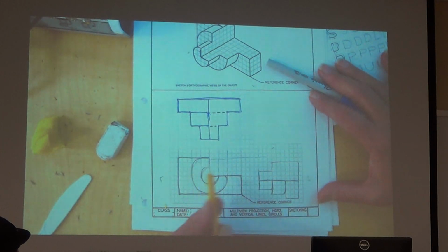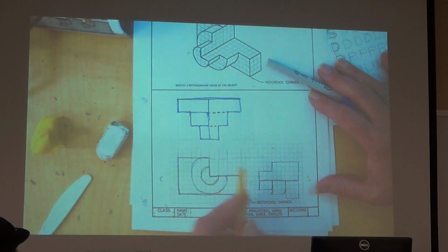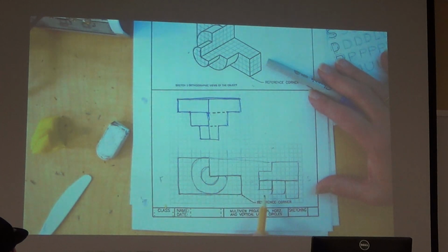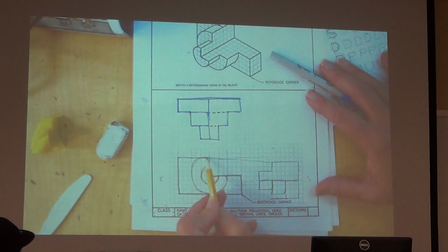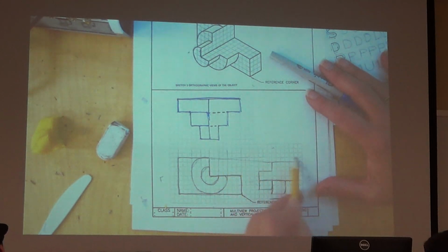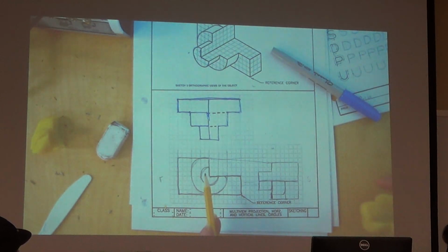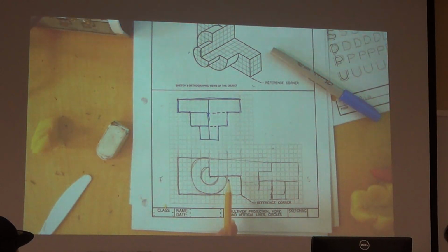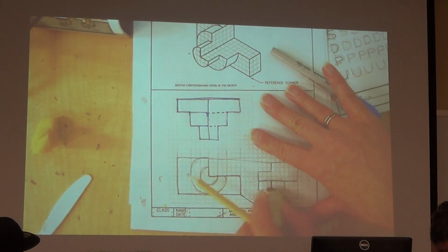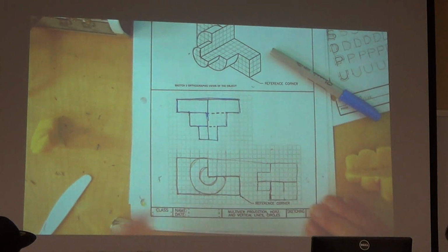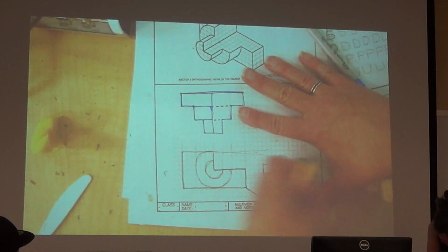It's not lined up, but let's say it's off by the bigger circle. The middle one, the radius is 4. So it needs to be down here. But you see what I'm seeing now? This is off, because this should be carried over. So it should be like this, and then what? Hidden one on the middle circle. Your center line's off, top line's off, everything is off, your radius is off. Let's just go.